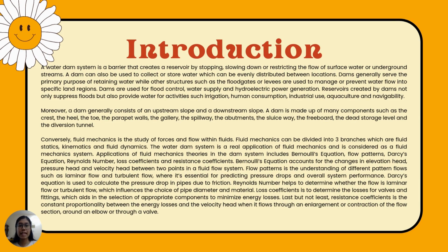Application of fluid mechanics theories in the dam system includes Bernoulli's equation, flow patterns, Darcy's equation, Reynolds number, loss coefficients, and resistance coefficients. Bernoulli's equation accounts for the changes in elevation head, pressure head, and velocity head between 2 points in a fluid flow system.